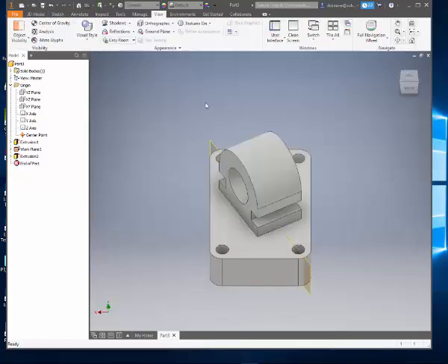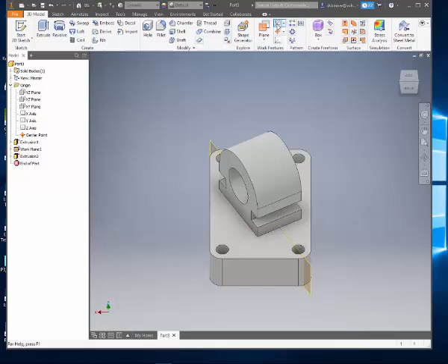I want to put a hole in the top of this part. Remember we talked about this before. It's difficult to get a work plane off a curved surface. So if we can draw that hole on any plane that's inside the circle, then it would cut all the way through this. So I'm going to create a plane. Go to the 3D model tab, and I'm going to create a plane, and I'm going to offset it from here. So I'm going to left click, hold my mouse, pull it up, and it gives me a dialog box, and I'm using 0.75.